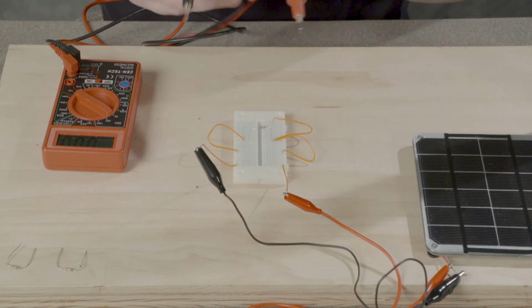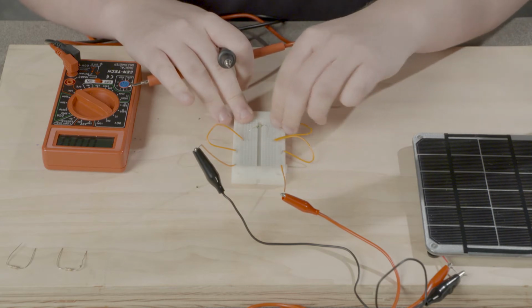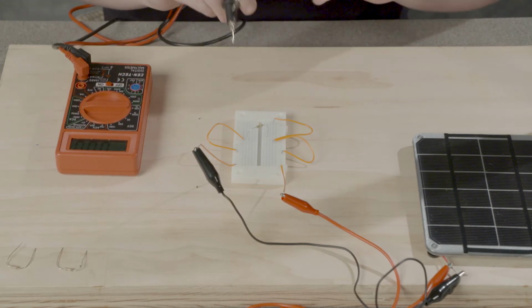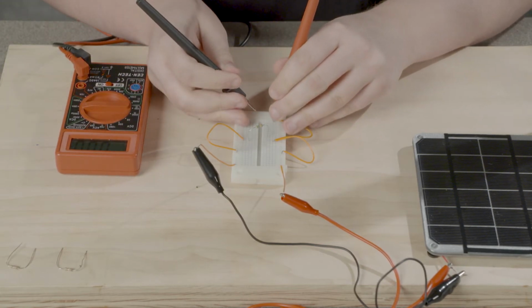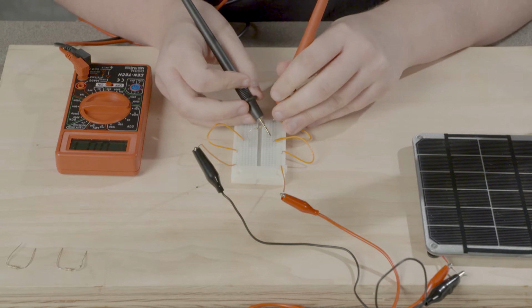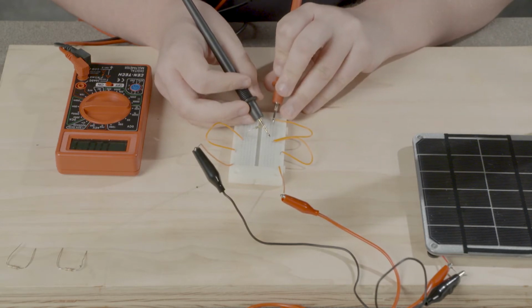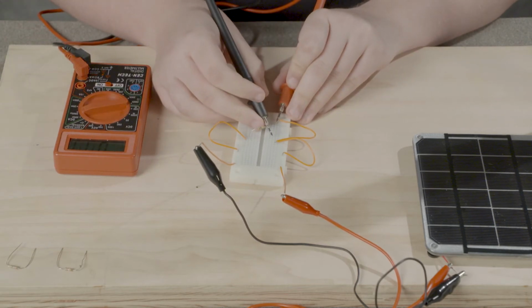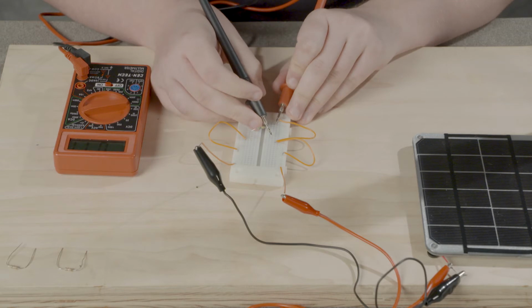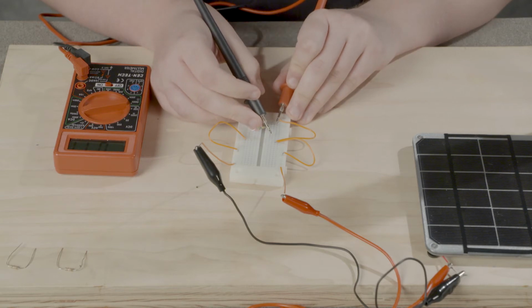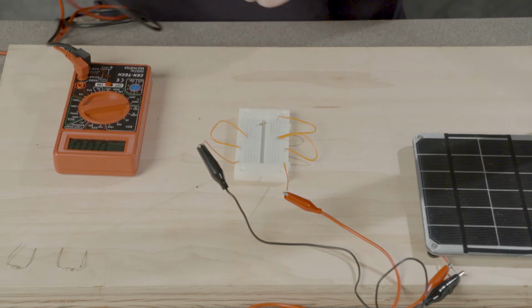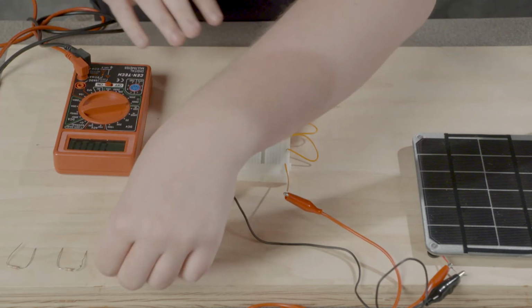All right. Take this out. So there's only one pathway to go. Put this on to 20 milliamps. And let's connect the multimeter in series. Okay, let's see if we can actually get it. Oh, let's try this one. Okay, and that's 11 microamps. And yep, that's exactly what we got. It's just converting units, so that's exactly what we got. So we're good.